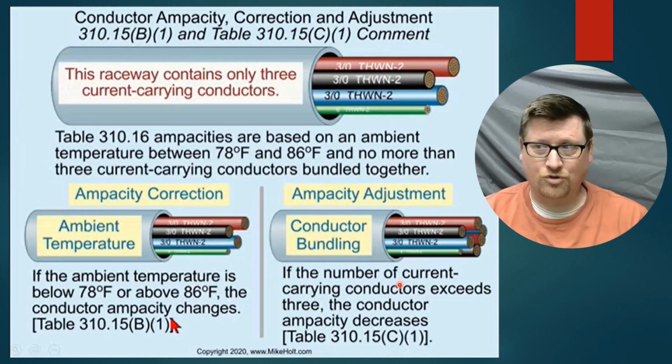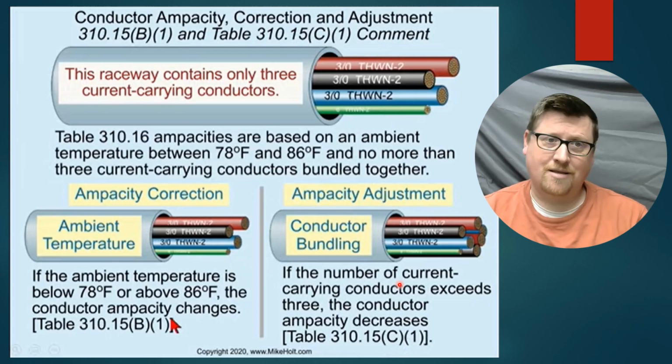But when you're stuffing that many in there, I'm having to derate those wires to such an extent that it's probably not worth it, right? It's going to be more advantageous for me to use smaller conduits with a limited number of circuits in each one of those conduits when I'm choosing to run these wires and these circuits from one place to another, so that we don't get into situations where we've created an overheating situation.